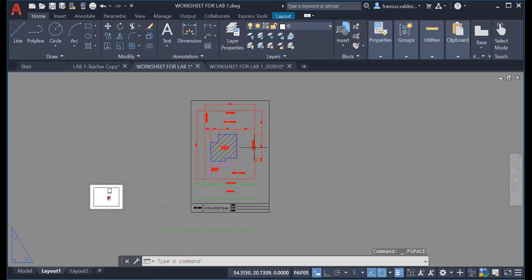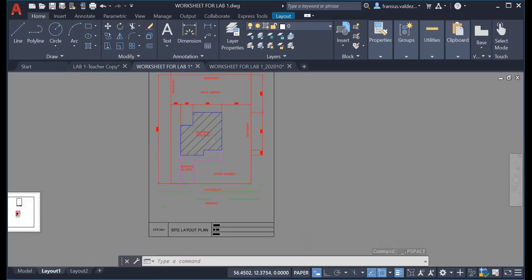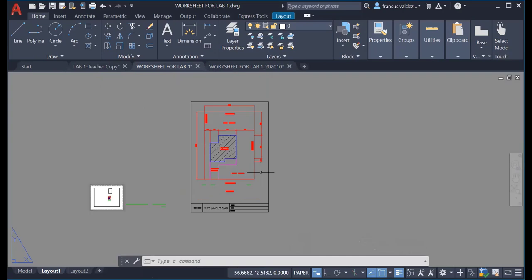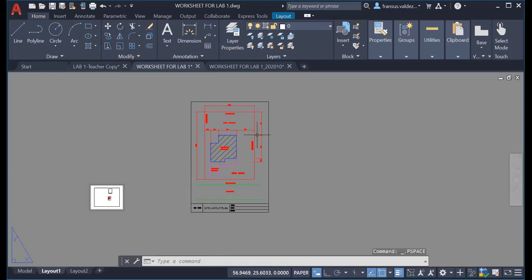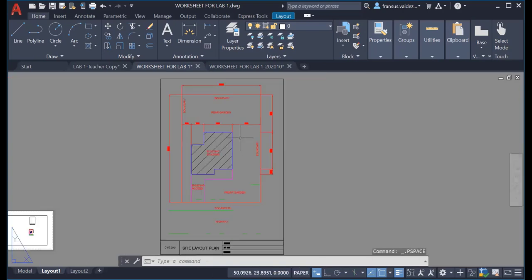So here, now once you double click this one here, you can never change it anymore. Now, if you want to change it, double click again, and then you'll see the highlight, and then you can change zoom, scale, and change the scale either 1XP, 2XP, 1.5XP, it depends. I will teach you this later on in the layout and printing. In the meantime, let's use 1XP. That's the common denominator. And then once this is 1XP, double click inside, and you have this one. This is exactly 1:100 scale.